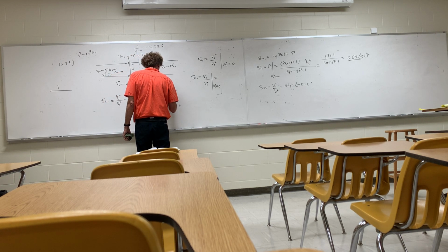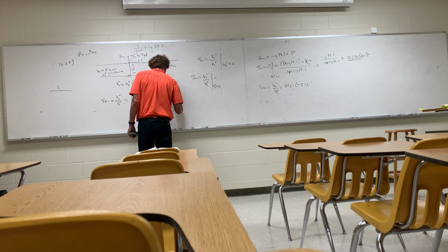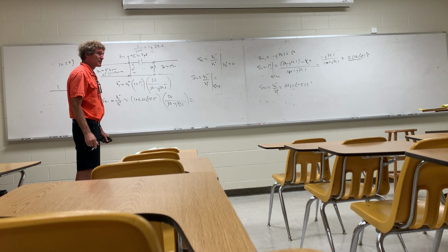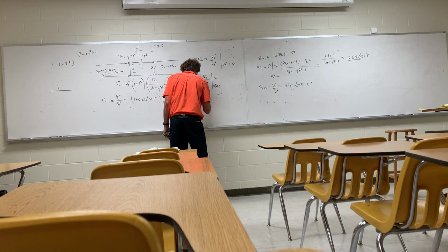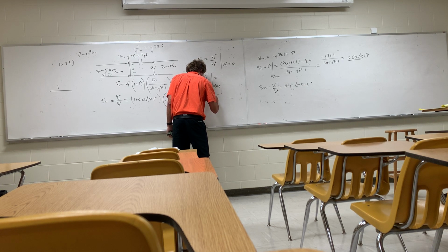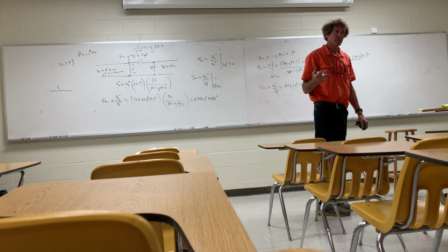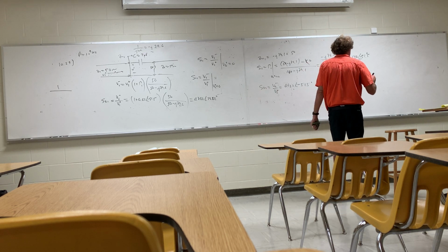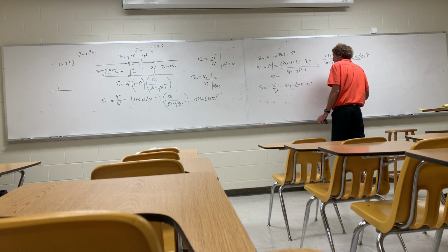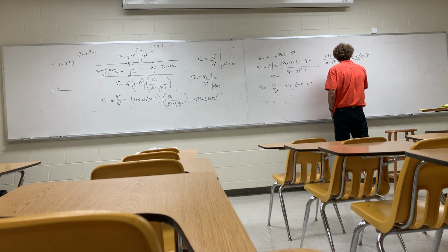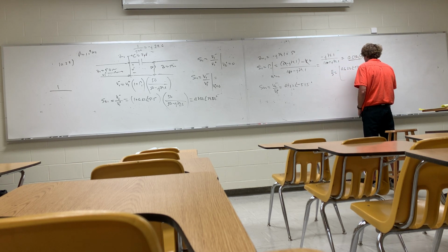I have to take that, then multiply it by 50 over 50 minus j79.6. You can see how this is going to take you a little time to calculate. All right, magnitude and angle: 0.782 at an angle of 38.52. Now, if that's S21, you see how that's going to be S12 because it's reciprocal? Y'all follow me? So I'm going to put the S parameters of that thing right here. I'm going to have my S matrix equal to, and for S11 equals S22, it's 0.623 at an angle of minus 51.5 degrees.